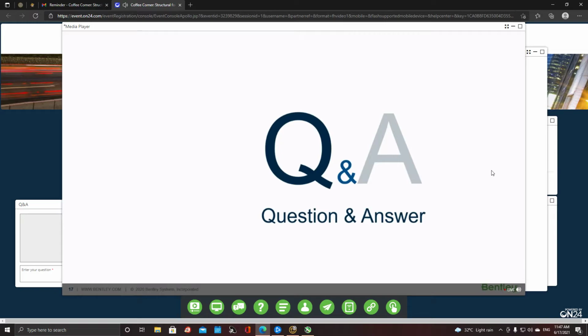Note that you're not limited to only the options available in the wizard. The wizard will help you get most of your modeling done. That doesn't mean that 100% of the modeling and loading has to be done with the wizard. After you bring the model to the main graphical user interface of the physical modeler, you can use any tools to model any loads. It could be wind load, seismic load, or this filter media load you mentioned, which can also be modeled as a point load, member load, or plate load using the usual features of StaadPro.